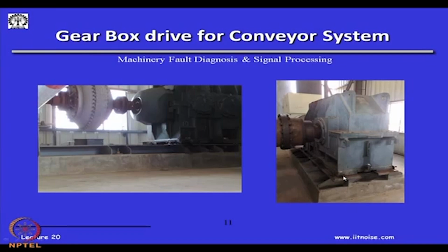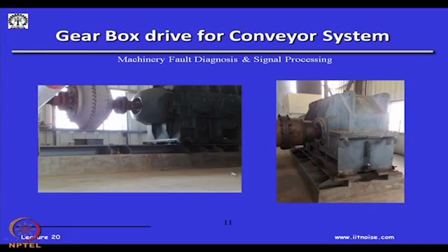And to ensure that the vibration levels are less than the levels allowed as per the ISO standard, we have to monitor at all these possible locations, 18 locations in this case, 18 into 3, 54 channels, and see what the highest levels are and whether they qualify the vibration standard. In fact, in this case we had situations where the manufacturing was so poor that the alignments were not done. There were a few welders, I do not have a better view here, but they were lying because this was used to unload raw materials from the ship.